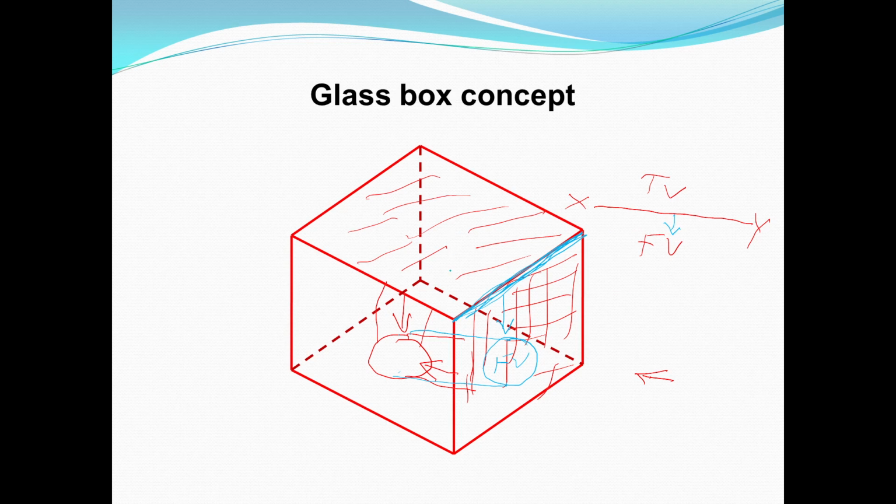And we get the top view, the projections, if we are looking towards the object from the top through this plane, we get the projections on this horizontal plane. So this one is the top view. So the top view, after rotation of the horizontal plane in clockwise direction, this part will come above the xy line. So top view above the xy line, and we are talking about the third quadrant.